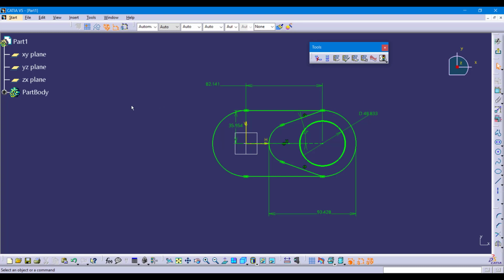You have also created a new branch of your tree. To see this, I am going to expand my specification tree underneath of that sketch. You have a 4th sub-branch under that sketch called Outputs, and you can see that it's registering that you outputted that one circle.